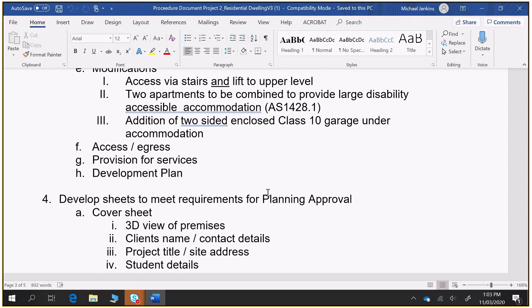So have a think about materials and finishes that you want to do on this to dress it up. Rendering brickwork is probably a good idea because that enables you to move windows around wherever you want, because it will hide a multitude of sins. The knockdown process? When you say multitude of sins, you're talking about not matching bricks and all that. Exactly, not matching bricks. Because trying to match bricks is going to be a nightmare for 1960s, 70s brickwork.